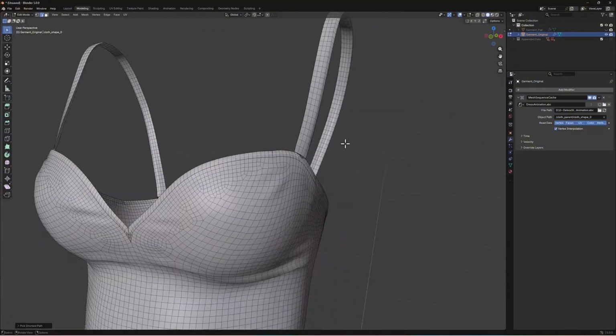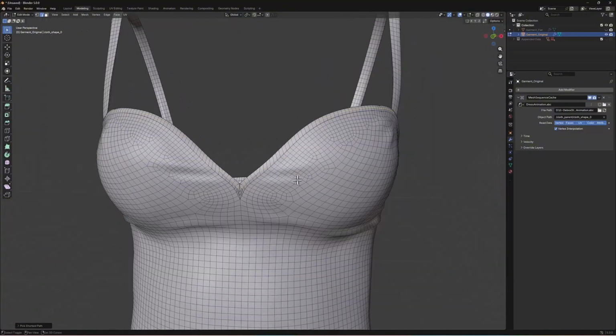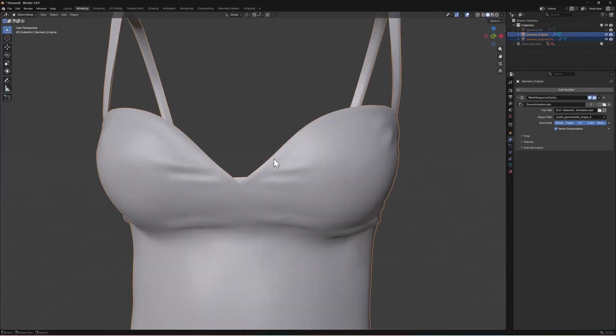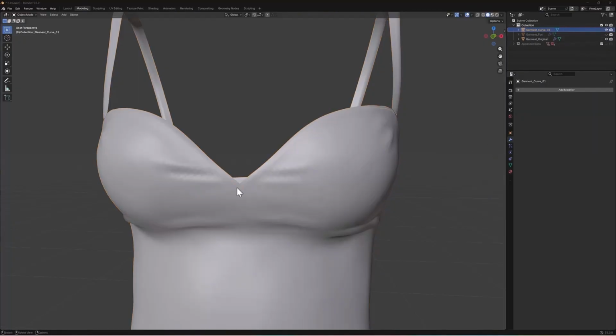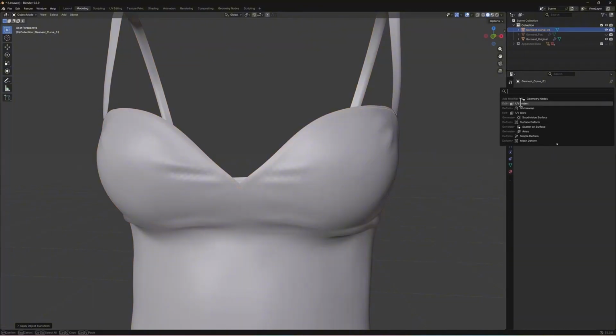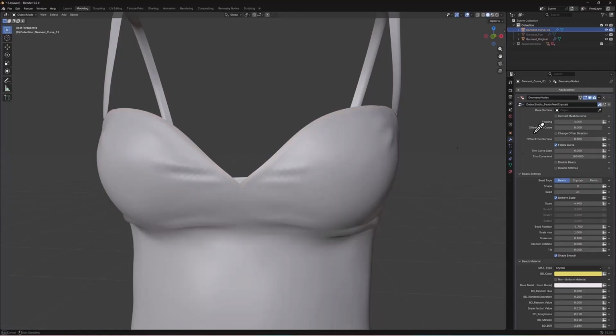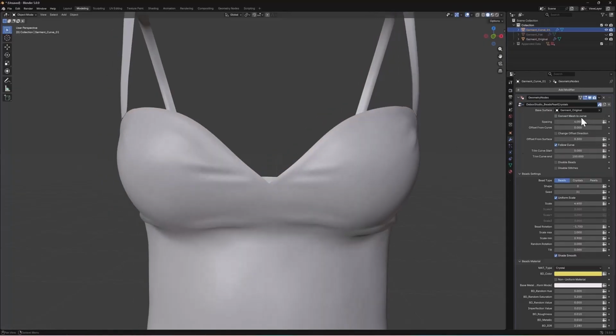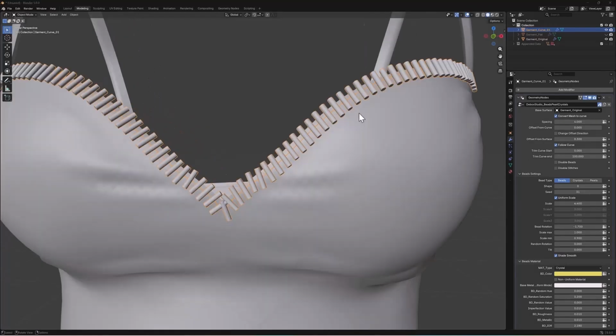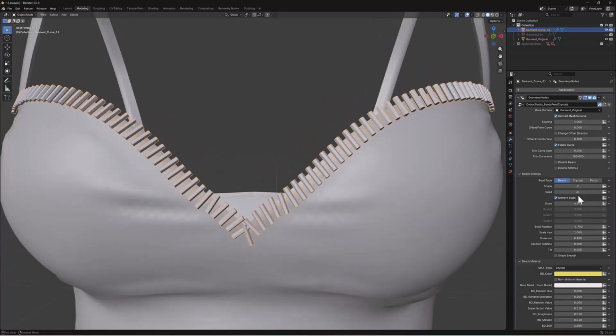Now press P to separate the selection from the original model. Rename the object and remove the Mesh Sequence Cache modifier from the duplicate curve so you can see it. Make sure to apply all fastmode to the object and add a geometry node modifier. Choose the tool you want to use. Now you have to check the Convert Mesh to Curve checkbox because we did not convert it to curve before. Now reference the base surface and tada. You can modify the curve anytime to have better bead placement.